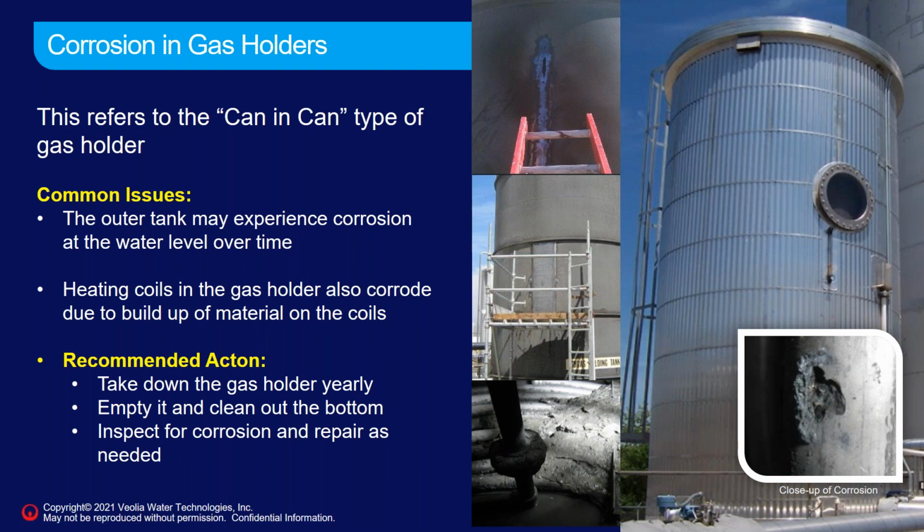A lot of the older ones we did were coated carbon steel, so you have to inspect the coatings as well. Some of the newer ones we've been doing are all stainless steel, so you don't have to worry about coatings as much. But again, you still need to look for mechanical wear and potential fouling in the bottom from the makeup water. Next.